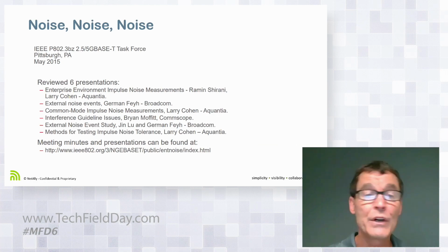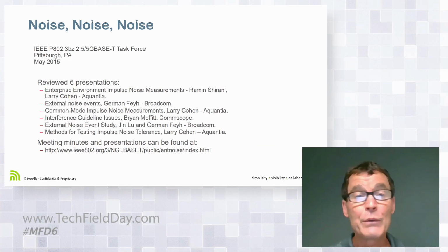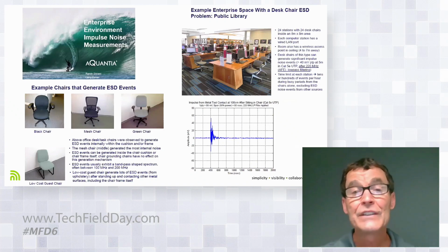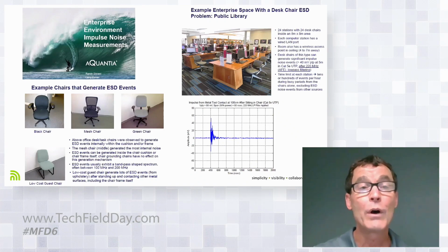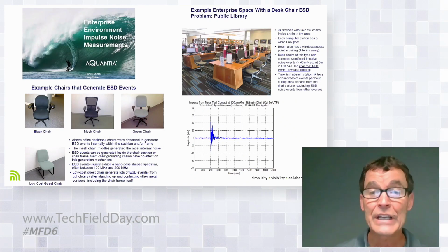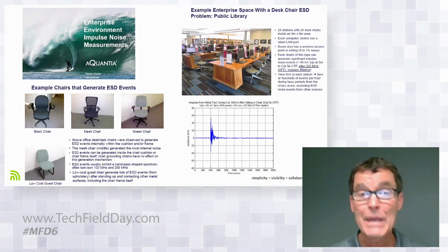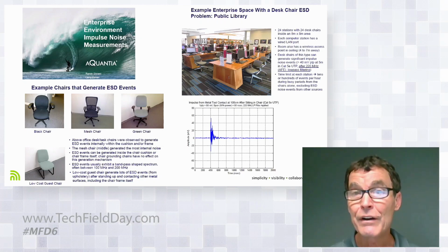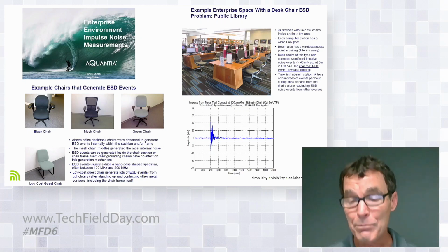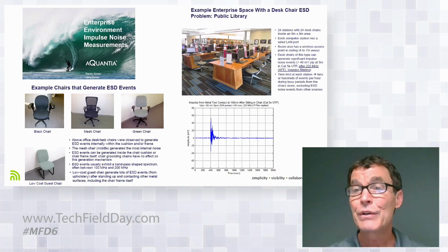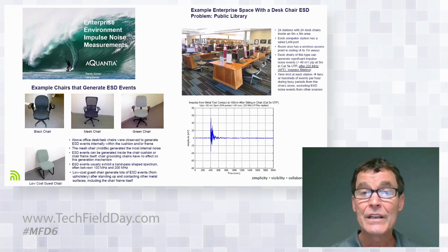What's the test bed for noise? How are we going to do this? And I thought one of the coolest studies there was done by Quantia, and it was on ESD, right? Literally, it just came down to the fact that just getting out of a chair can throw a pretty good ESD shock a pretty far distance, and you need to look out for that.